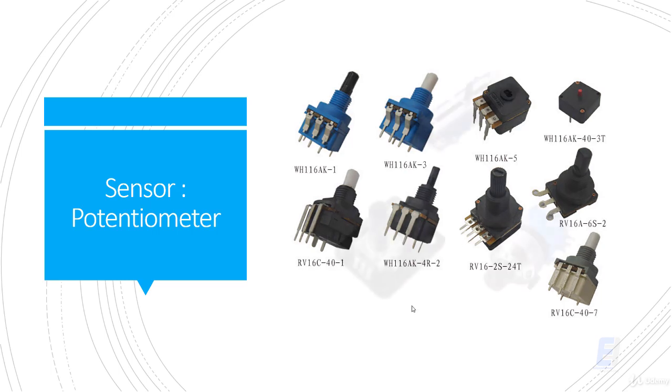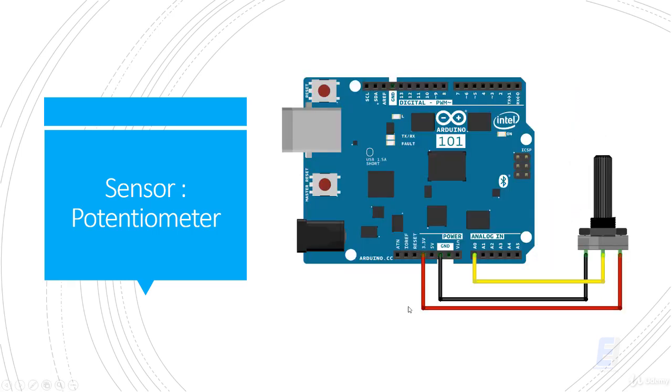The circuit of this lesson should look like this. Connect the potentiometer to pins A0, 5 volt and ground. The middle lead is the one to connect to the analog pin, and the voltage varies on this pin. The orientation of the other two pins does not matter.